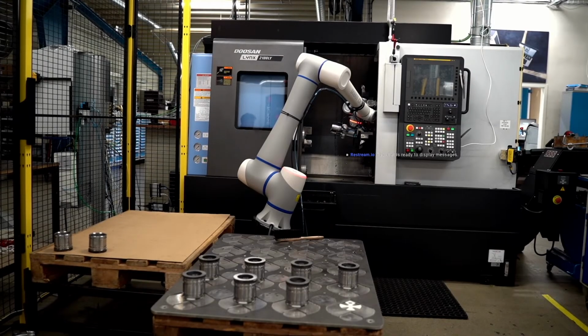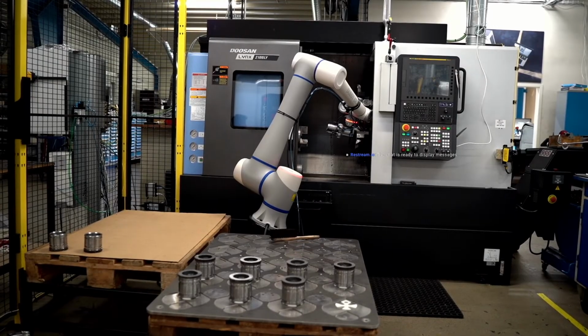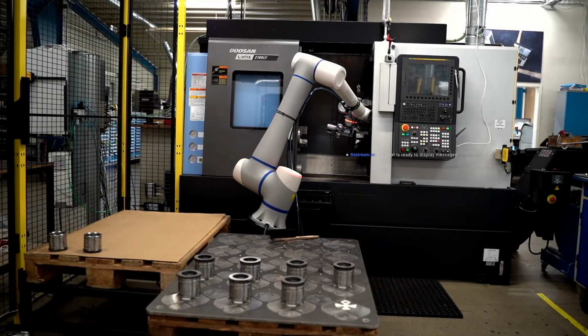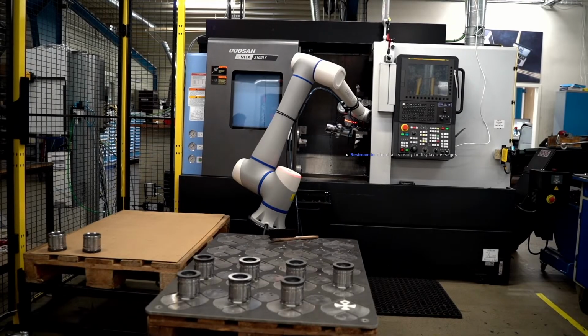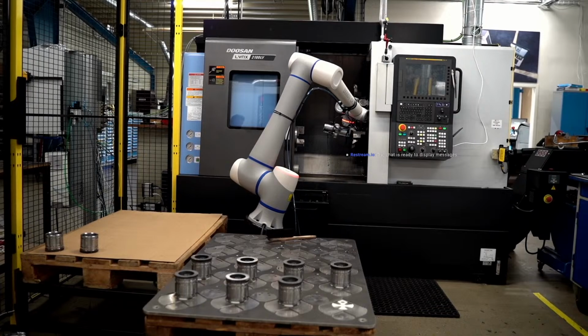So you can see, I do this, and the robot turns red, which means it will not move. You use SICK nanoScan scanners, right? When people enter the working area, the robot will stop and wait for you to go back and push the button to confirm. Exactly, there is a safety button to release the safety. Okay, now I understand more or less how the robot works.